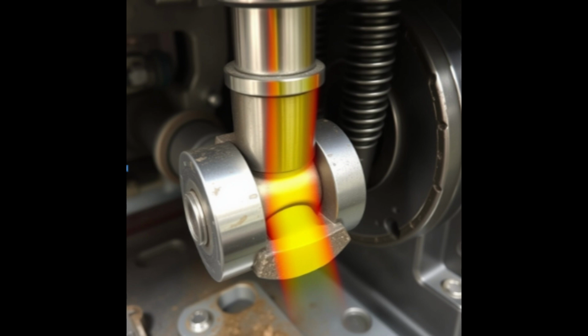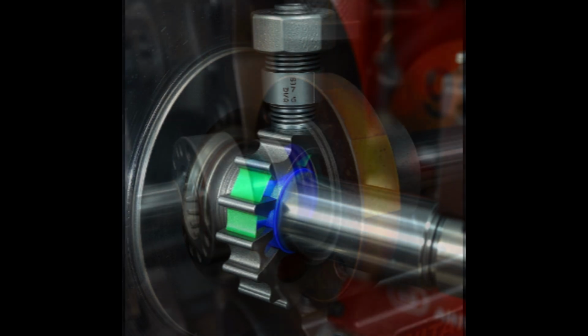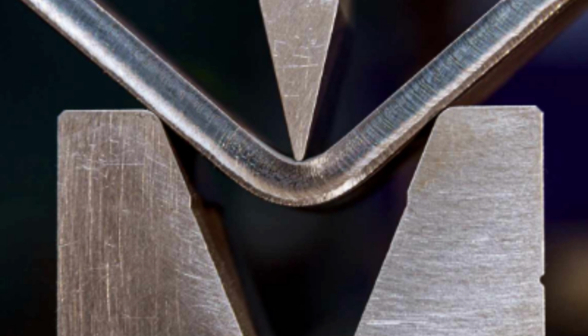Appearance. In materials under bending stress, you'll often observe curvature or deflection. The side under tension may begin to elongate, while the side under compression may shorten or even form slight ridges. If the stress exceeds the material's limits, cracks can develop on the tension side, especially near points of maximum bending, like the middle of a beam.